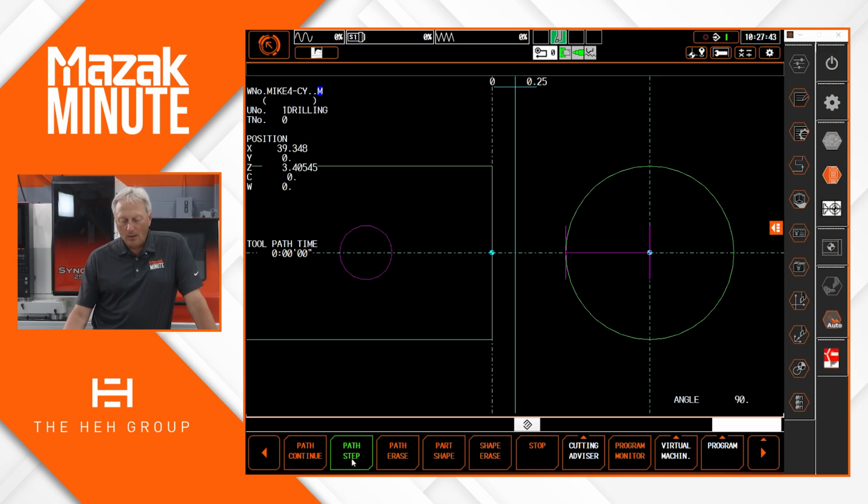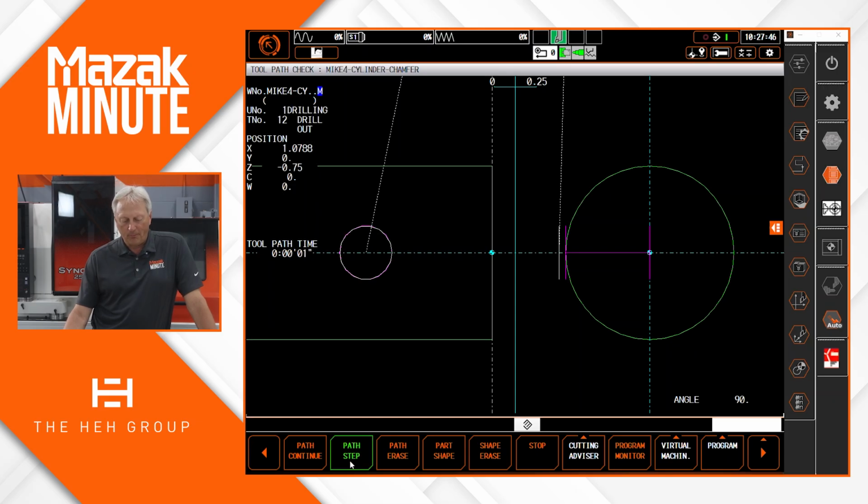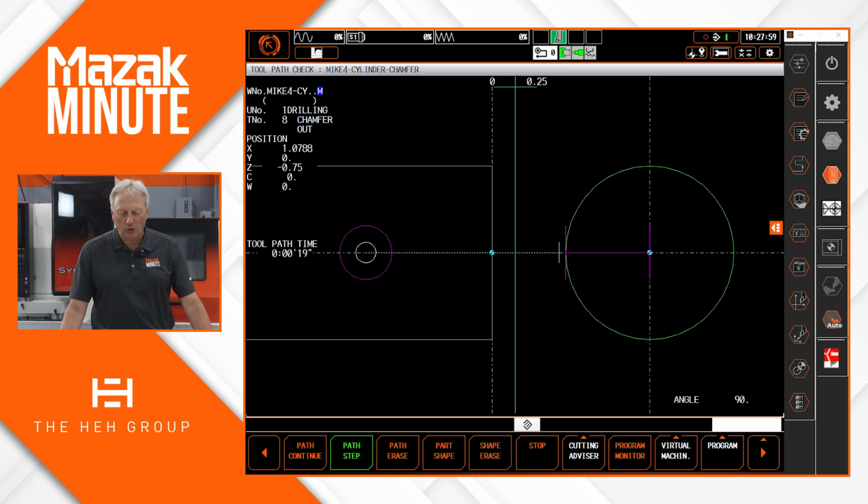I come over. This is going to be the drill hole. It drills down. It comes out. I'm going to go ahead and hit path erase. And now I'm coming over with my chamfer tool. Remember I chose that 1/8 chamfer. That chamfer tool is above the X, above the diameter. Y is in the center line. Z is there. C is at 0 degrees at that 12 o'clock position.